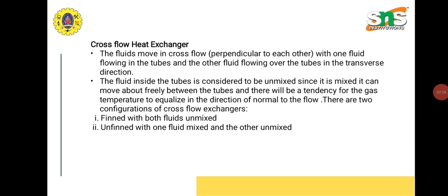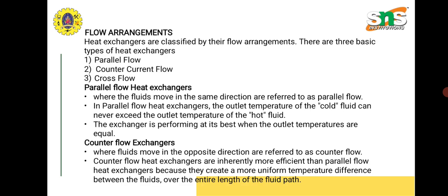Cross flow heat exchanger. The fluids move in cross flow, with one fluid flowing in the tubes and the other fluid flowing over the tubes in the transverse direction. Finned with both fluids unmixed, unfinned with one fluid mixed and the other fluid unmixed. Flow arrangements: parallel flow, counter current flow, cross flow.